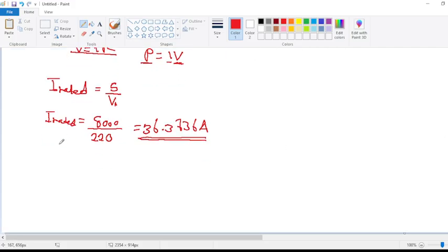So from there now we can calculate the power, the copper losses. We're going to have the power of the copper loss at full load. Don't forget about this: the copper loss at full load has to be equal to the power of the short circuit, you multiply everything by the rated current, and you divide now by the current under the short circuit.